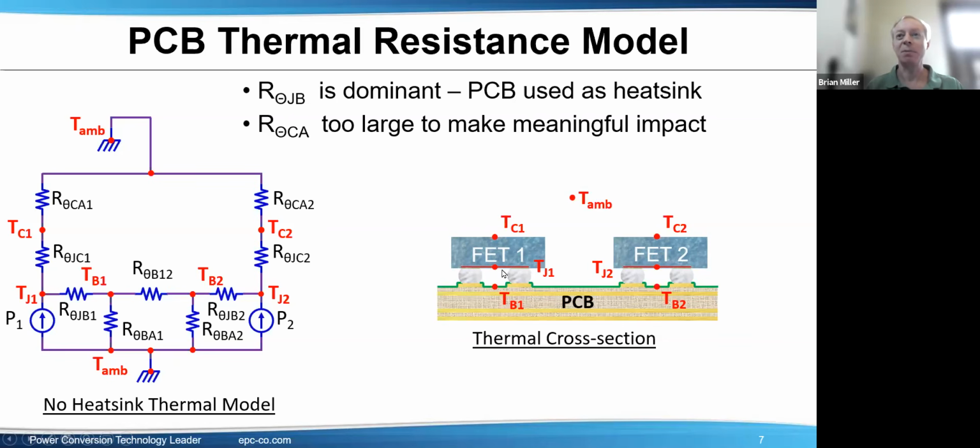That's polyimide, which is basically the non-brand name for Kapton. So you could say the Kapton tape already comes on each GaN FET on the bottom, even though it's not the tape form of it. So putting it on top should be okay. But again, I don't know the thermal conductivity of Kapton tape.